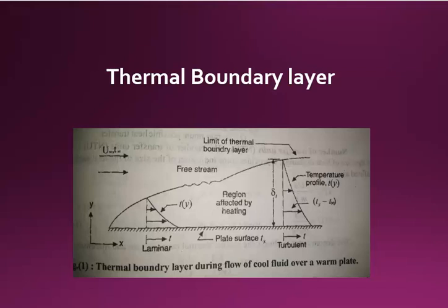As the fluid flows along the wall, the fluid at the wall surface satisfies the no slip boundary condition and has zero velocity. But as you move away from the wall, the velocity of the flow asymptotically approaches the free stream velocity. The temperature at the solid wall is Ts and gradually changes to T naught as one moves towards the free stream of the fluid. It is impossible to define a sharp point at which the thermal boundary layer or velocity boundary layer becomes the free stream. Yet these layers have well-defined characteristic thicknesses given by del T and del V.